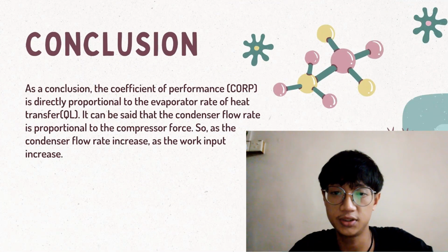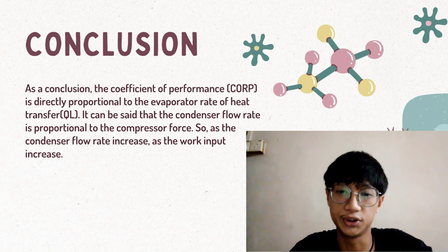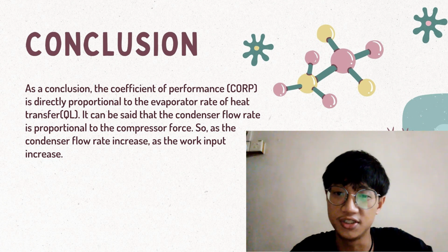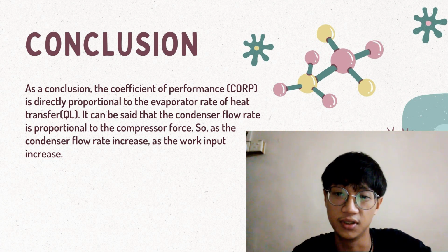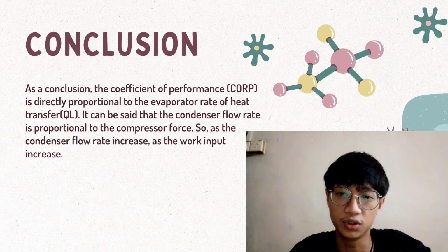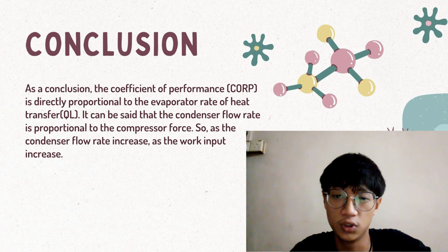Lastly is the conclusion of this report. As a conclusion, the coefficient of performance, COP, is directly proportional to the evaporator rate of heat transfer QL. It can be said that the condenser flow rate is proportional to the compressor power. So, as the condenser flow rate increases, the work input will also increase. Thank you.